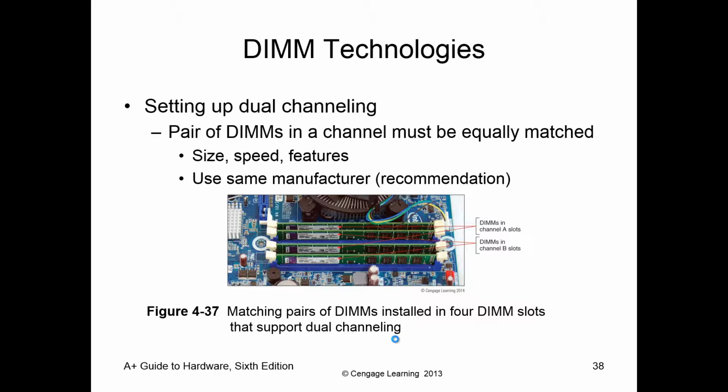So how do we set up our dual channel, tri-channel, quad channel? You check the documentation to verify that the motherboard supports it, and then you follow the instructions in the motherboard. In this example, it's 2 black, 2 blue, and so you line them up: 2 in blue, 2 in black, thus dual channel. However, don't always think about the color being the definition. Check the manual. Don't just assume that the colors show that it's dual channel.